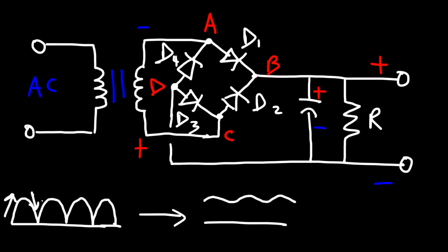And once the voltage is rising again, the capacitor is going to absorb energy again from the circuit, preventing the voltage from rising too quickly. And so by the capacitor absorbing energy and releasing energy to the circuit, it causes the voltage to be more consistent rather than falling quickly and then rising quickly. It smooths out the pulsating DC signal.